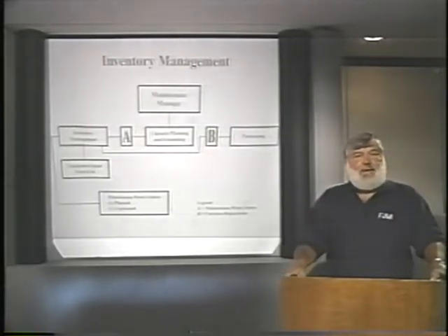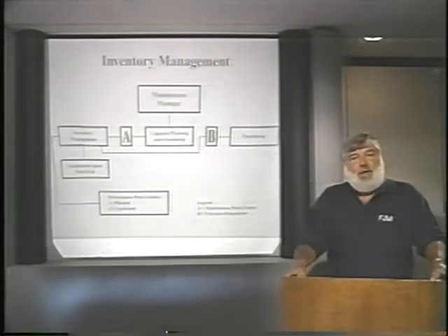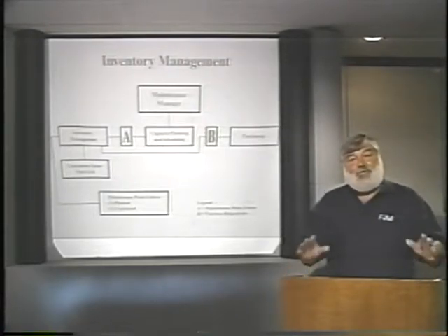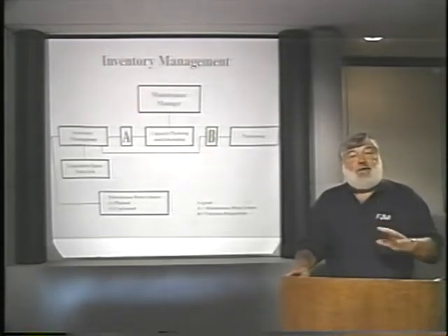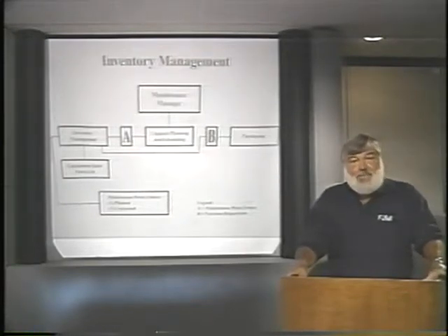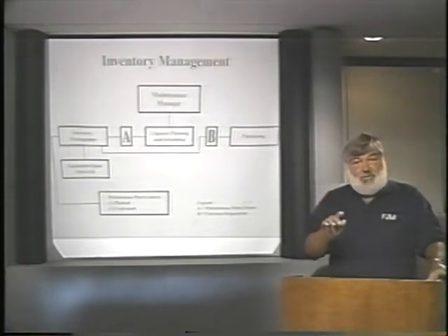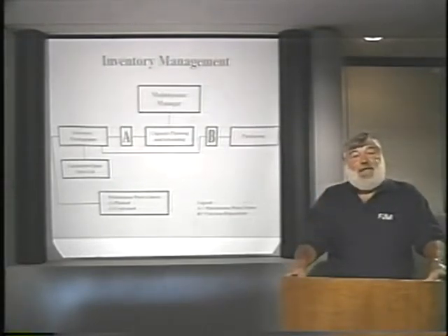Going back to a comment that I made a few moments ago about the 1 to 2 years to install a PM program. Once you've completed the development and implementation of your PM program, you're going to find that there's going to be a ratio between planned work orders and unplanned. The most common ratio that we have seen for non-continuous manufacturers is 80% of all the work orders are planned and approximately 20% are unplanned.